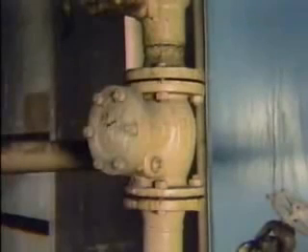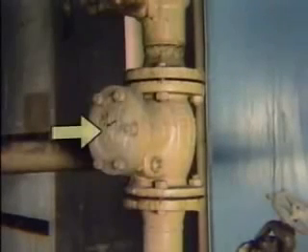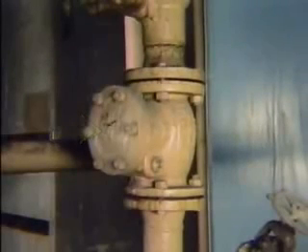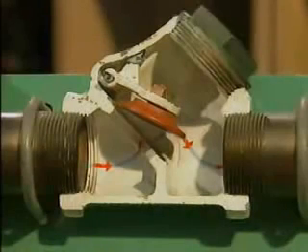The body of a check valve is similar to the body of a globe valve, but most check valves don't have stems, handles, or hand wheels. Most check valves do have replaceable seats, discs, and caps. The cap is the top part of the valve body, which can be removed to provide access to the disc for maintenance. It's essentially the same as the bonnet on other types of valves. Several different types of check valves are available. We will look at three of the most common.